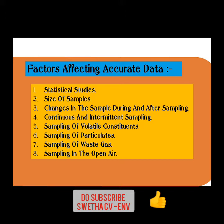Along with that, it is very difficult to maintain the isokinetic condition during sampling in the outskirts, because depending on the pollution and external factors, it will vary. For example, wind speed and direction will vary. Meteorological things, like if it is raining, again disturb it. So depending on these, they affect the accuracy of data. Okay, so these were the conceptual explanations regarding the factors which affect accurate data.